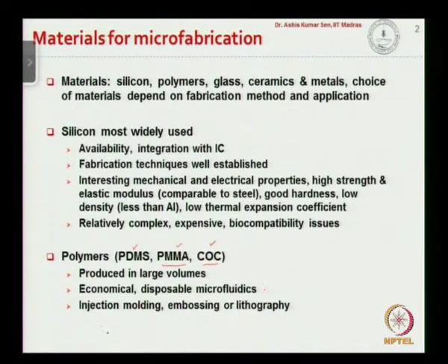The different fabrication techniques that are available to make polymer based microfluidic devices are injection molding, embossing and lithography. In injection molding, we have to make a replica of the structure, a negative of the structure that we want to make, and pressurize molten polymer material into that mold cavity, and then we can cool it down and remove the polymer from the mold. That is the injection molding process.